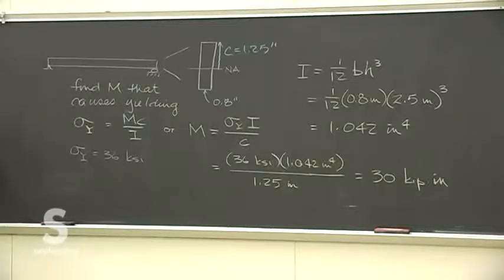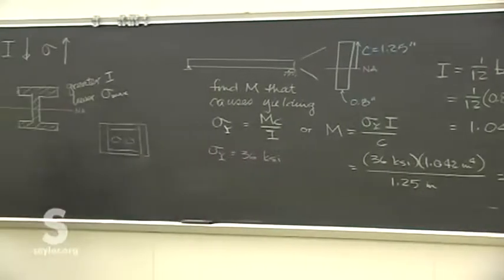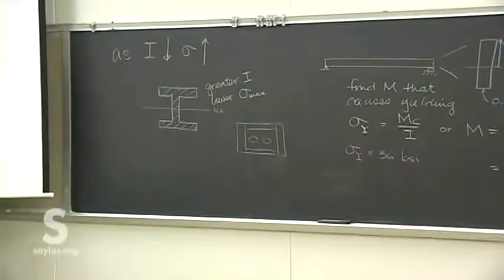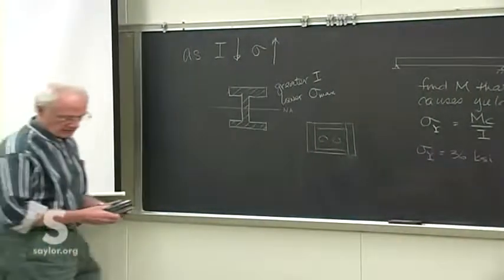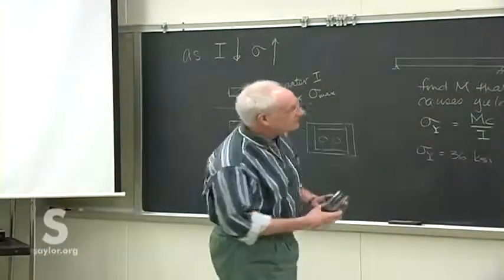It's pretty common to use built-up box beams, especially when you're working with wood. It's a really cheap way to get a lot of moment of inertia, as well as a nice aesthetic look. When you have these, it looks like big solid beams, but they're really just built-up beams in cross-section. It's not uncommon, too, that you might want to run some kind of pipes or wires down those beams just to make the house look a little cleaner in appearance.